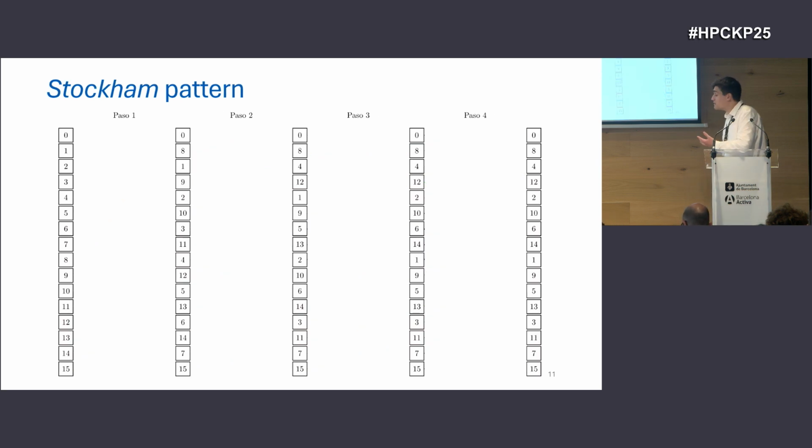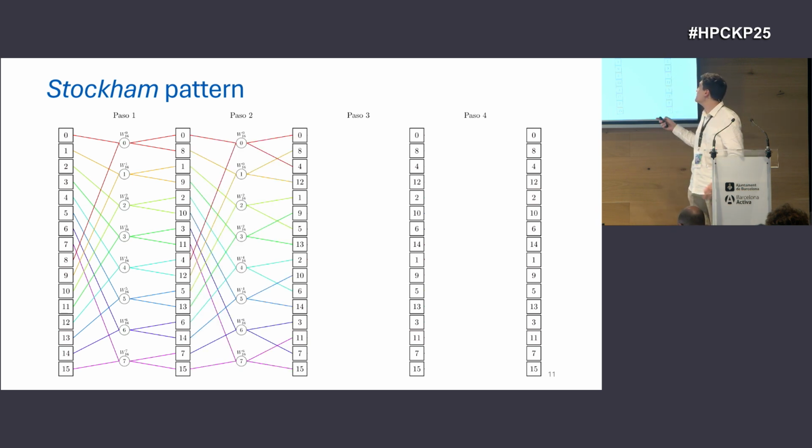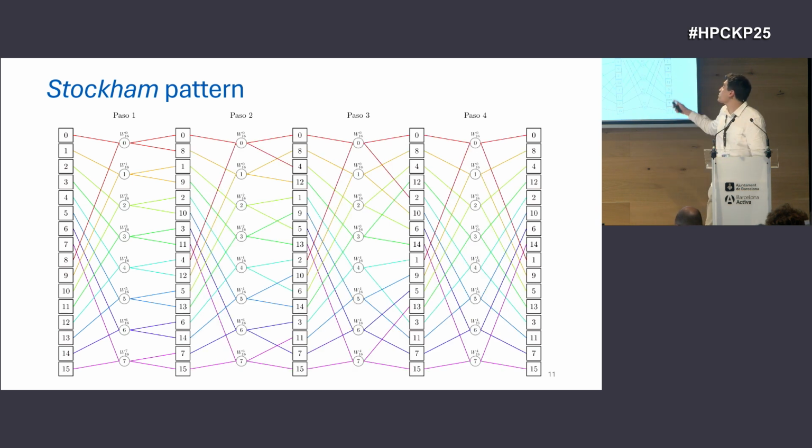The Stockham pattern is similar, but it combines the bit reordering step into all of the different phases. So we get a more complex data pattern at the expense of having one less step.